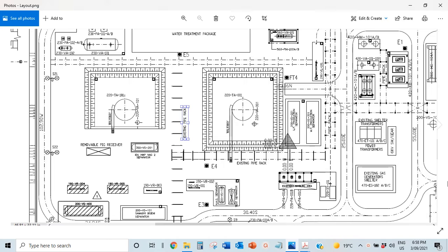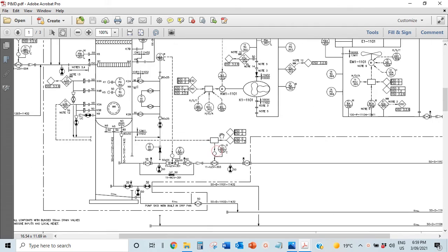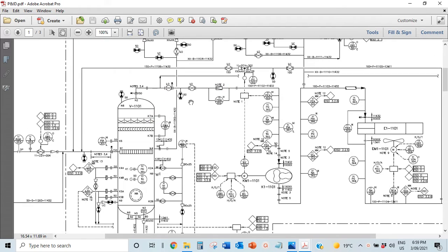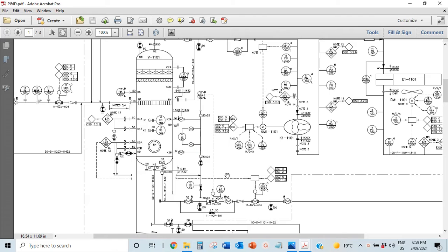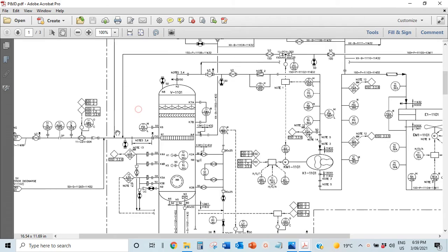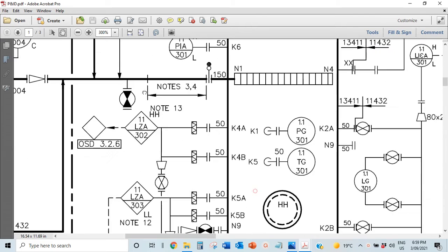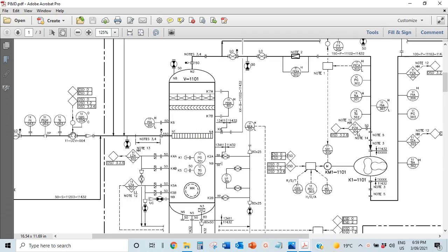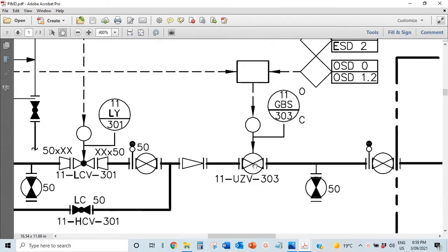But when the plant stops operating, you want to make sure that you don't have stuff still moving around, because gas can move anywhere easily, right? So you want to make sure that you shut them in. You lock in the gases and the liquids so that they don't flow around in a shutdown. So how you do that is you have shutdown valves. Here you can see for this vessel, you have a shutdown valve on the inlet. You can see that on the liquid outlet.